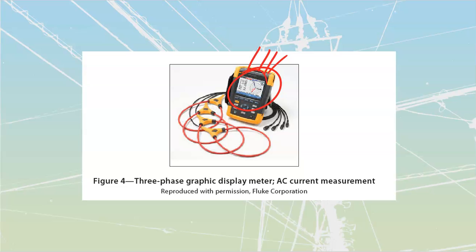Power loggers versus power quality recorders are a slight difference, but it's not a huge one. Really, the big difference between them is going to be the number of readings they take, the size of memory they have, and how quickly they can process multiple points of data. My power loggers are just going to grab all the voltages, then all the currents. They're just going to cycle through that, grabbing individual points, whereas these are going to be simultaneously grabbing all voltages and all currents at the same time, storing them.